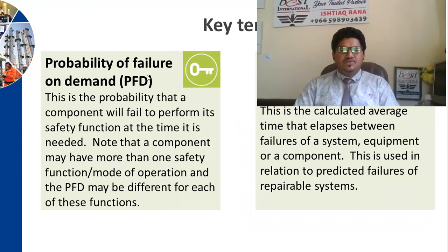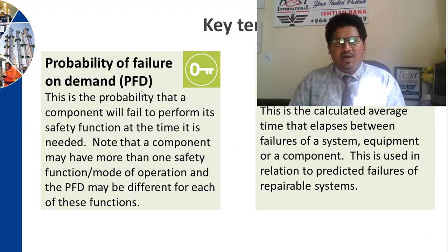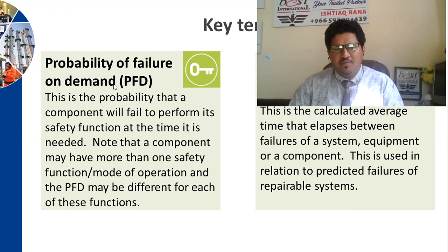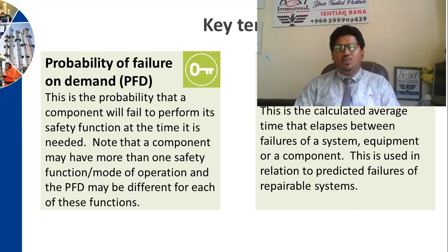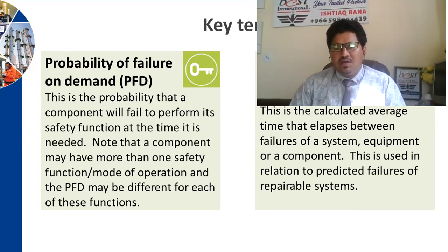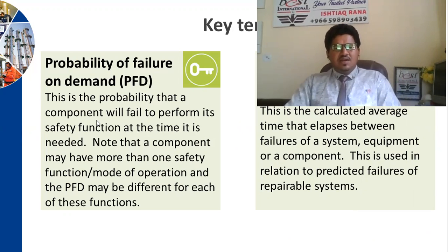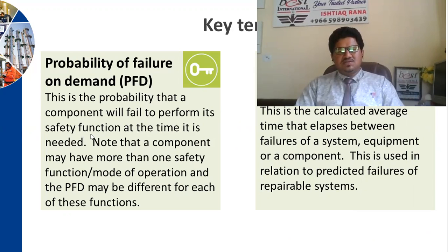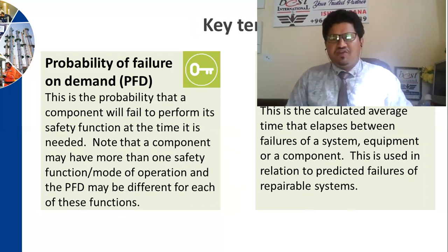The other key terms to understand are probability of failure on demand, PFD, and mean time between failure, MTBF. PFD is the probability that a component will fail to perform its safe function at the time it is needed. Note that a component may have more than one safety function, and PFD may differ for each of these functions. So just remember that this is the probability of failure on demand.